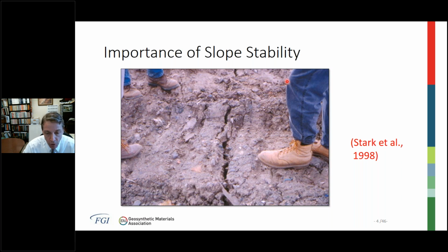And that gets to the importance of slope stability with geosynthetic lined slopes. The deformations that show at the surface are generally significantly smaller than what is being experienced by the liner system and the geosynthetics underneath of it. So after some discussion, it was decided to excavate the waste in this particular site. And I'm now going to take you to the liner system. Remember, the tension cracks that you saw on the top are only about 1/2 inch, certainly less than an inch.